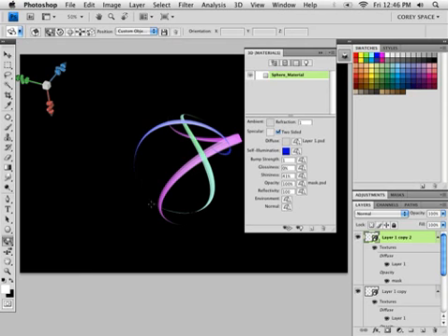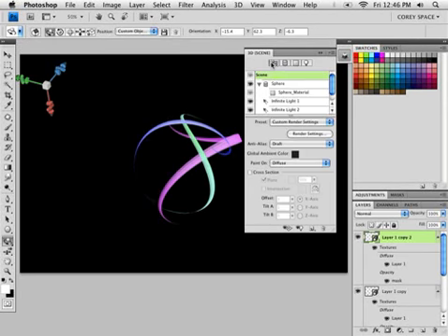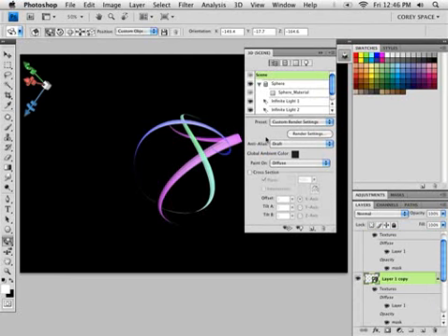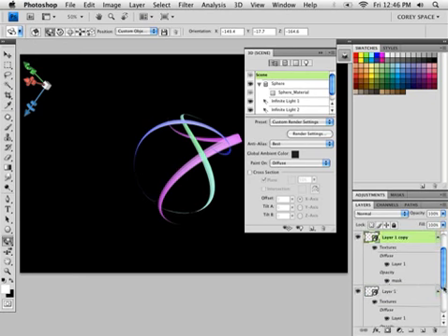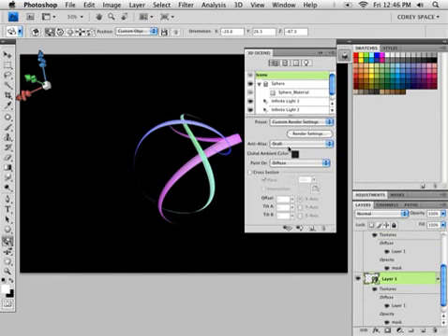Now, you might see a little bit of rough edges going on in here on all these layers. Let's simply go into the first item here, and that's the anti-aliasing. By default, it's set to Draft. Let's simply change it to Best. And it should smooth out those lines on each one of these objects, making it a little bit more appealing. And we'll do that on this very last one here. Set that to Best.